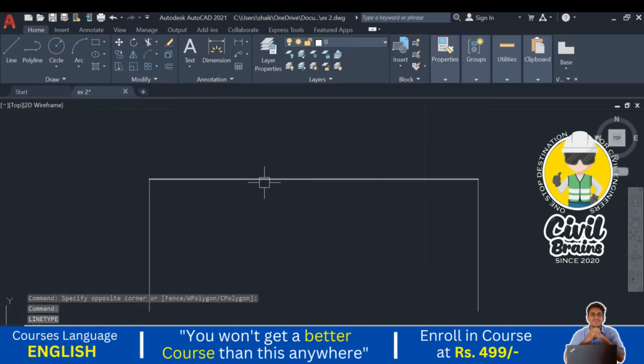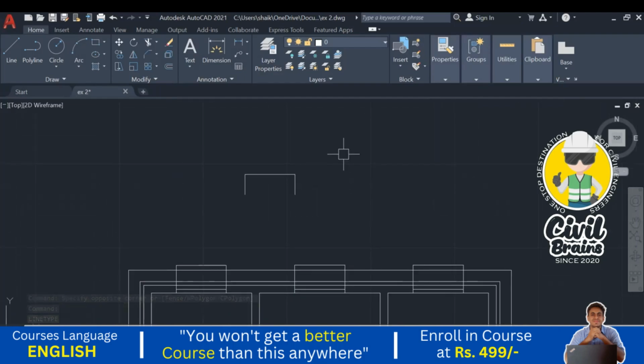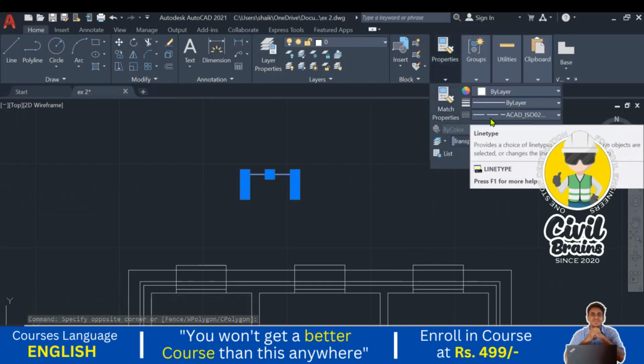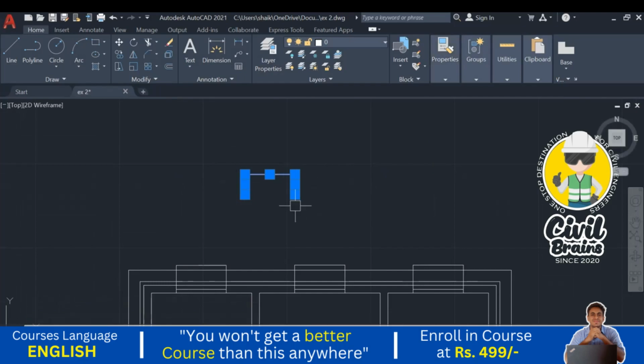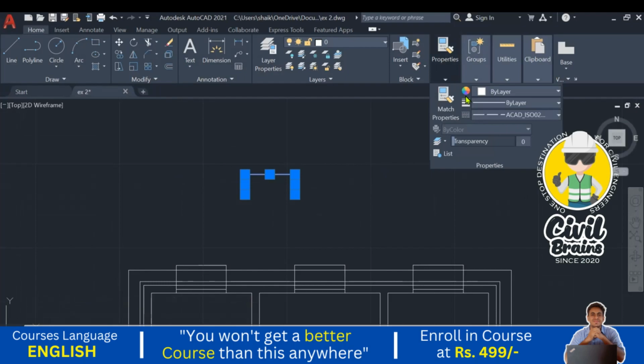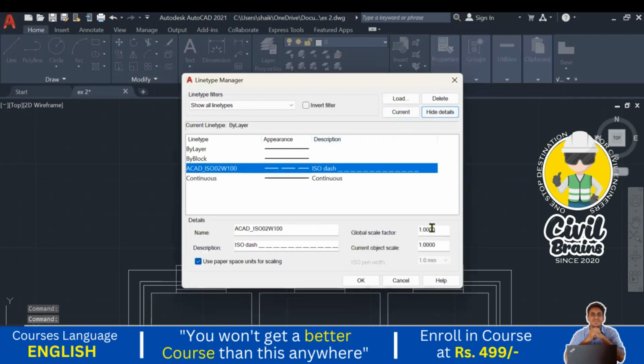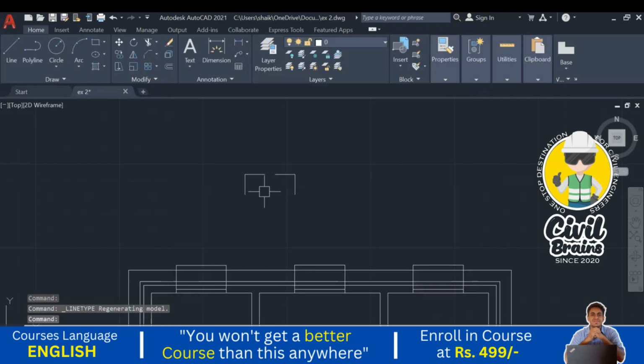So here you can see this one. It is not showing the dash line. I select again. I go to the property section. Here you can see it is a dash line, but here it is not visible. Why is it not visible? Because of the scale. Because of the scale. I go to others. I click on the dash line. I show details. I change the scale here. I change the scale to 0.1. Global scale factor, change. Press OK.